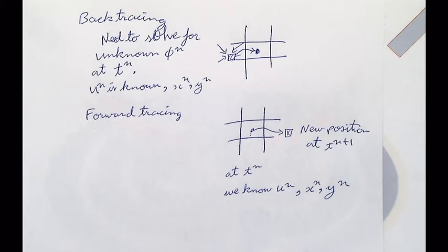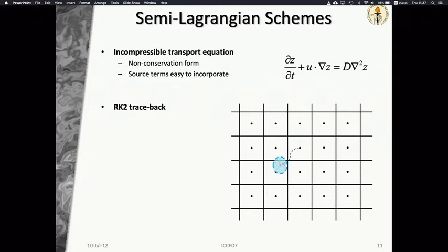So with that, let's go back to the picture I had drawn. This is exactly what we were doing in this schematic here. We were going backward in time to figure out where we came from. So we came from here. Now, what is the phi of this blob then? To figure that out, we do the interpolation from the surrounding grid points. And you don't need to just restrict yourself to this area. You can go to much larger areas. So should I go to as large an area as possible? That would introduce many errors. We need to keep the grid size as fine as possible.